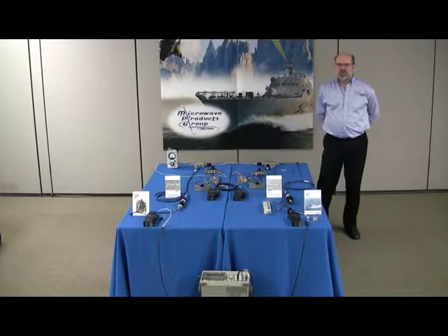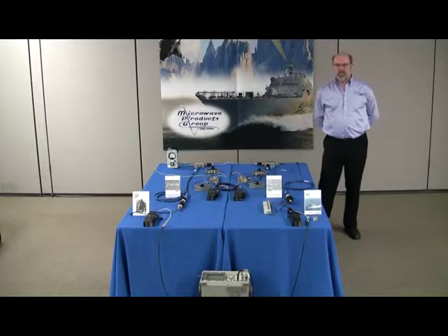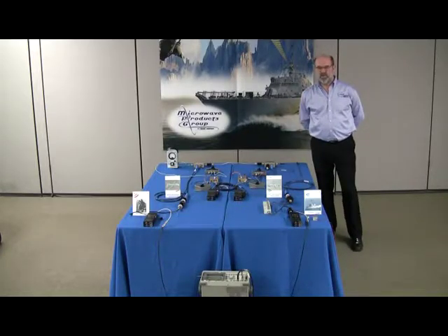Presumably, if Cosite interference is degrading the UAV's victim receiver sensitivity and therefore the radio relay's range, it should take less power from the uplink transmitter with Cosite interference mitigation than without to achieve the 12 dB output SINAD we desire. We will now make this measurement.